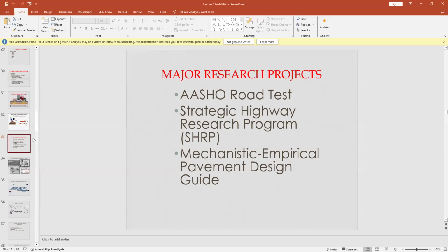Because from the 1950s, from 1956 to 1997, they were using penetration grade bitumen, 60/70, 85/100. But in the US, they started realizing that simply using this material is not going to be enough to sustain the rutting and low temperature cracking, as well as the fatigue cracking.